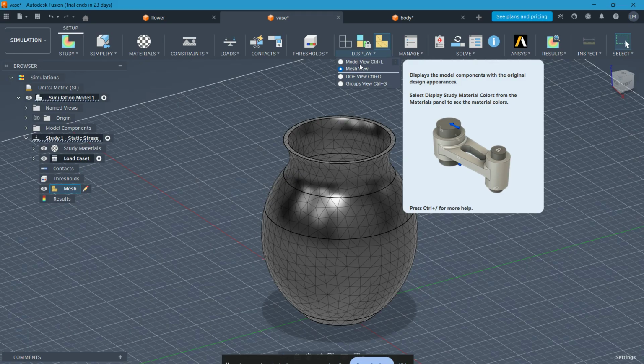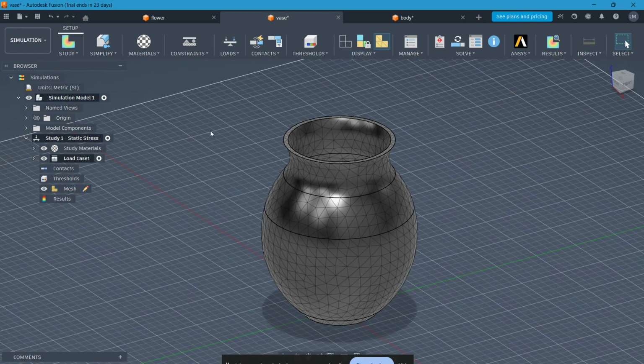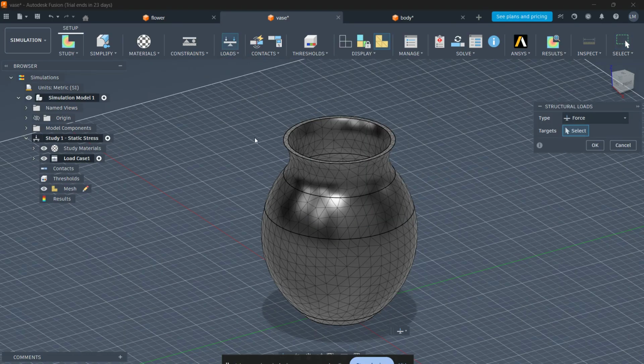You should also take a look at your simulation conditions. Unrealistic values like extremely large forces, impossible constraints, or conflicting settings can cause the solver to fail. Keep your inputs physically reasonable and consistent with real-world behavior.